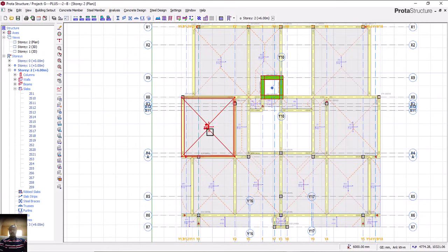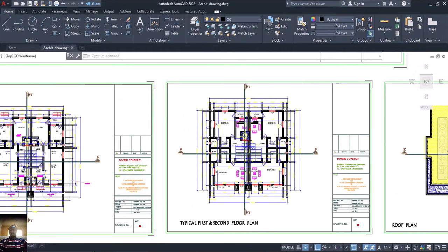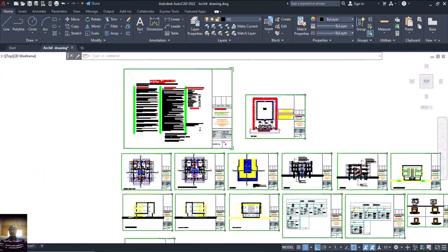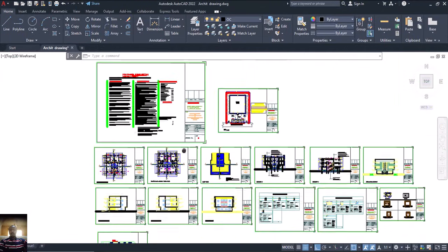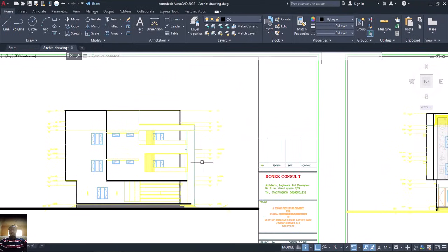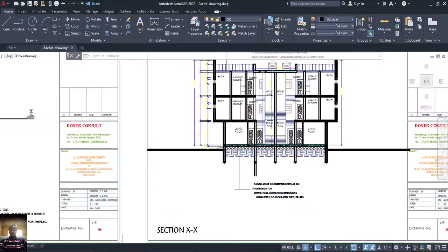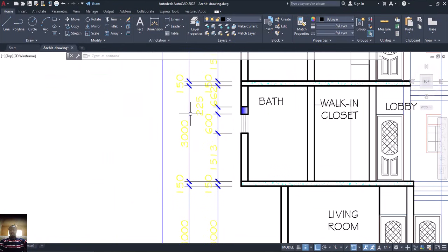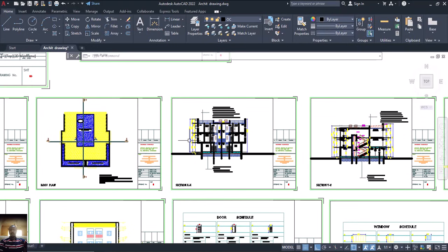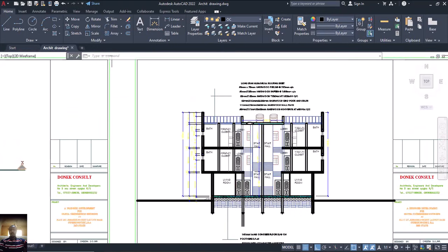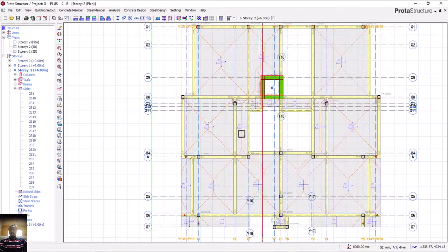But before we apply the line load, we need to know the height of this structure. I'm coming. It was written somewhere. The height should be here. Can you see 3 meters? It's 3 meters high. So that is that. I'll come here now and confirm. Come here, edit story. Let's see what we have there as our edit story.